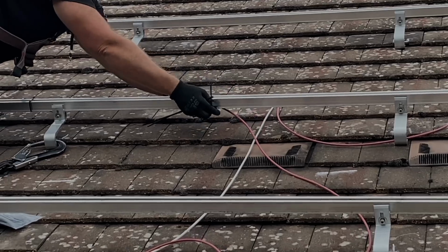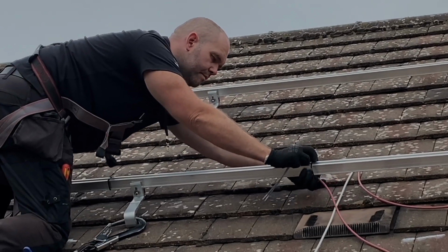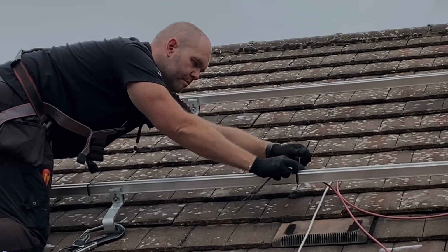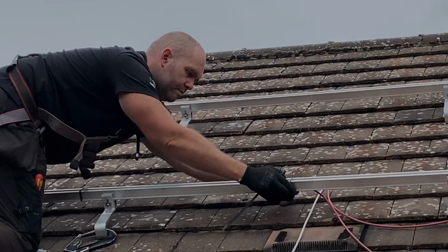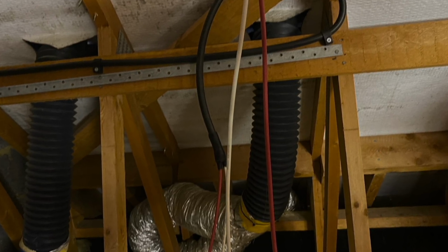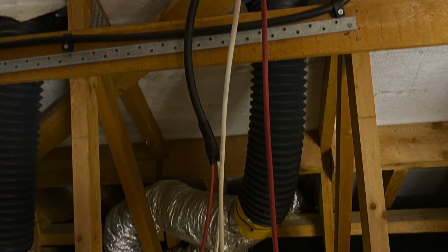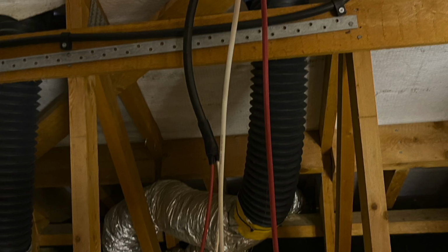The cables which are coming from the PV array need to be protected and contained together. You may find yourself with 4 cables which make up 2 strings, and it can be a temptation to install these cables in conduit or trunking. However, conduit and trunking capacities need to be considered, and you may find that 4mm squared PV cables will be too much for a 20 or a 25mm conduit.